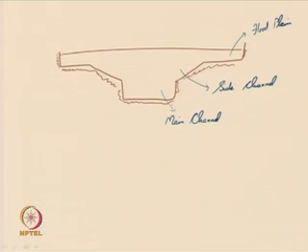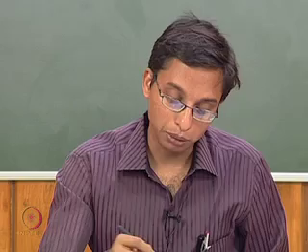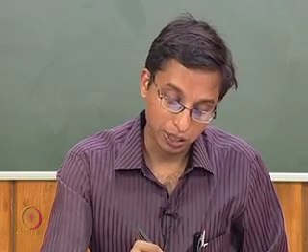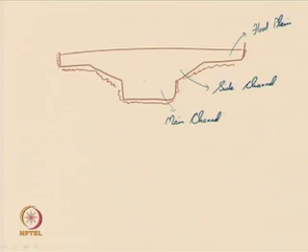If you are able to suggest that, now for each, for example, there may be some energy correction coefficient for the main channel, some for the side channel, and for the flood plain. They may be quite different also, there are definite chances, because for example, the flood plain is normally in a dry situation and when the flood arrives it gets wet.